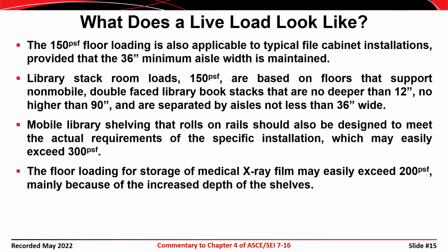And then if you consider the storage of medical files, X-ray film, for example, it might exceed 200 pounds per square foot because the film itself is heavier than paper would be.